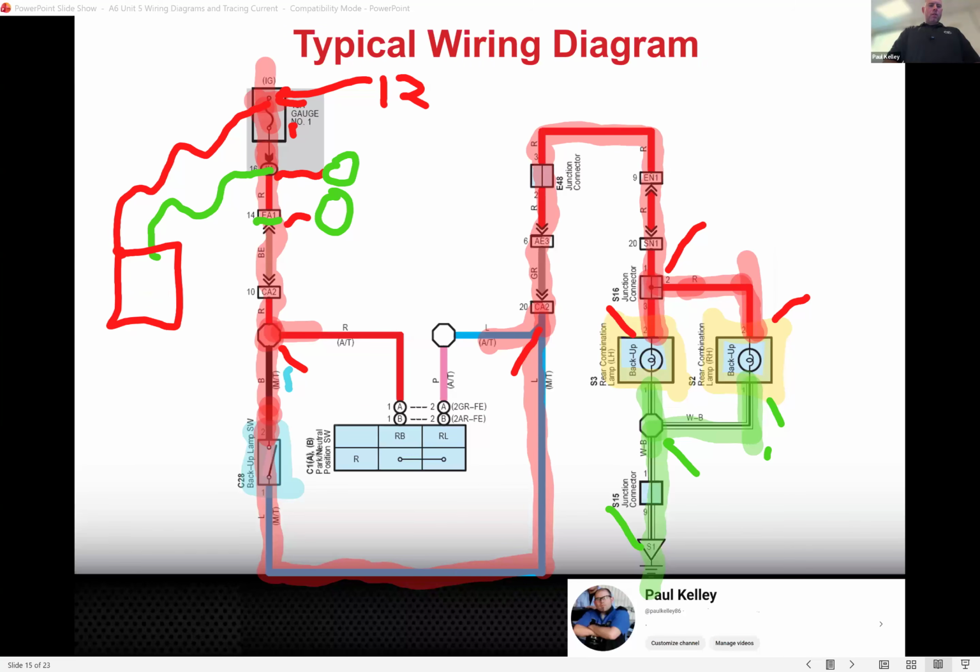All right, but let's say I got a different number now. Let's say that we fixed that one. We won't give any details as to how we fixed it, but we repaired it. Let's say I got 12 here and I got a 0 here. What do you think? Yeah, the switch is open, but what if I make sure the car's in reverse and the switch is still open? Yeah, there you go. So get a new switch.